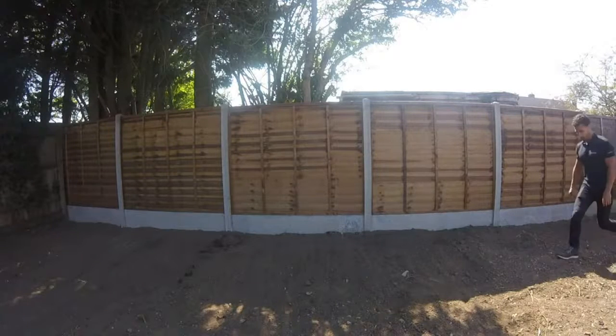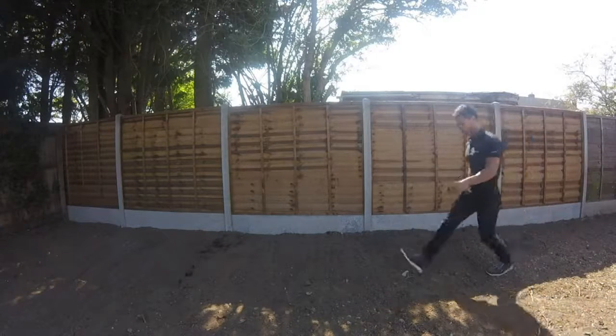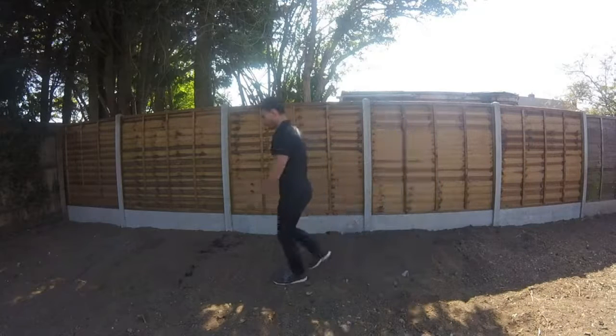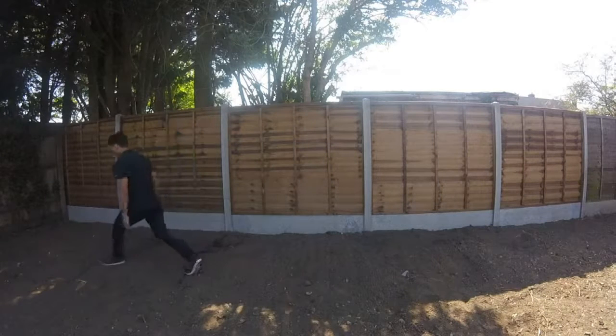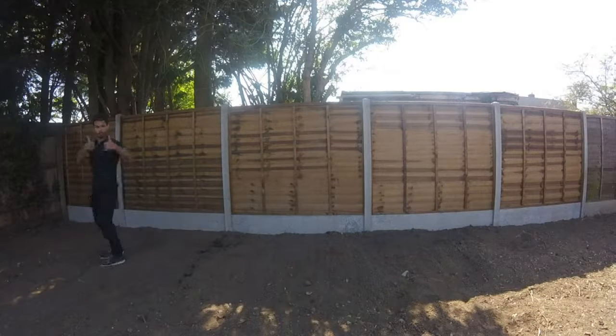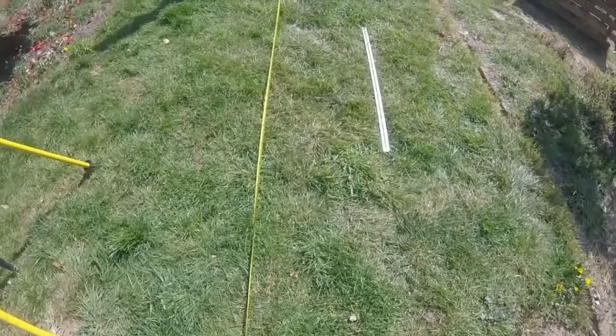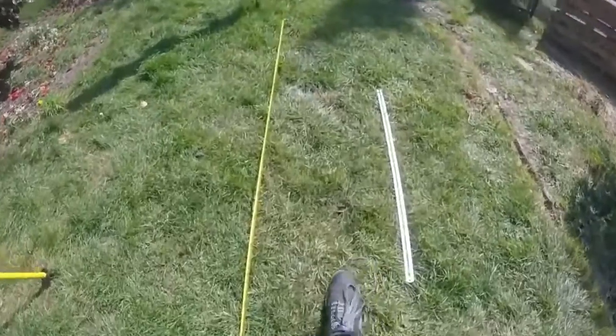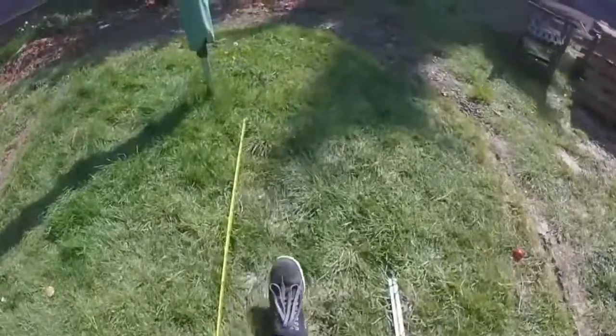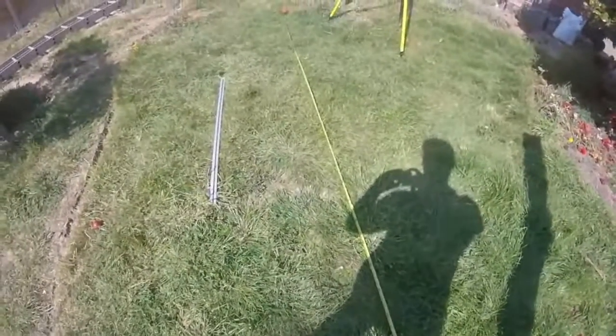Now what a lot of surveyors do is learn how long one of their strides or footsteps is. Even better, if you can learn to practice pacing out a meter, it will be easier to do the maths in your head. So I learned how to do this by laying out a 3-meter tape on the ground and practicing walking the distance in just 3 steps. Now I know that one of my paces equals 1 meter.